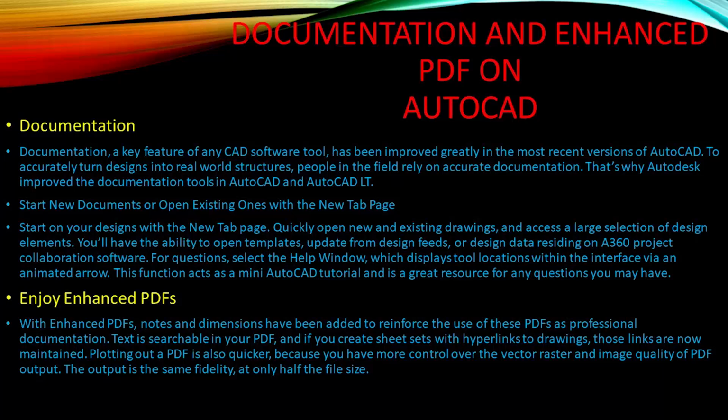Now, with enhanced PDF, notes and dimensions have been added to reinforce the usage of this PDF as professional documentation. Text is searchable in your PDF. If you create a sheet set with hyperlinks to drawings, those links are now maintained. Plotting out a PDF is also quicker because you have more control over the vector, raster, and image quality of PDF output. This output has the same fidelity at only half the file size.